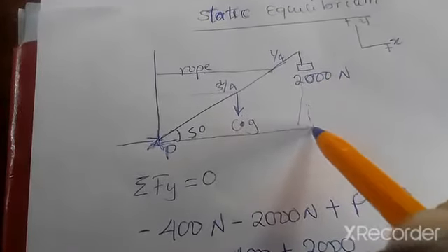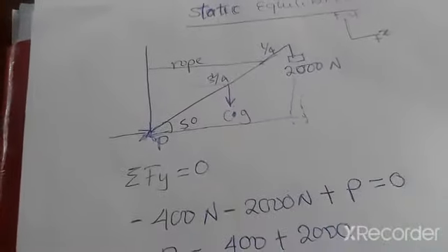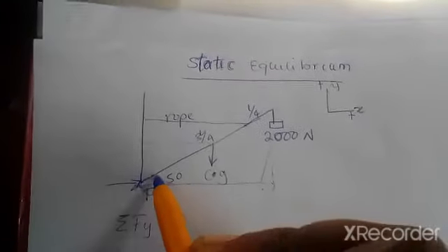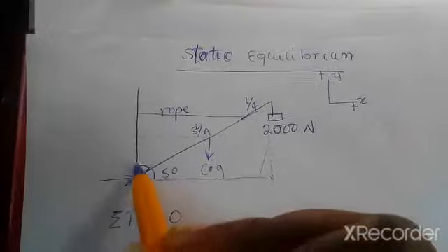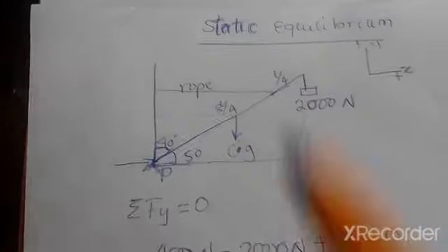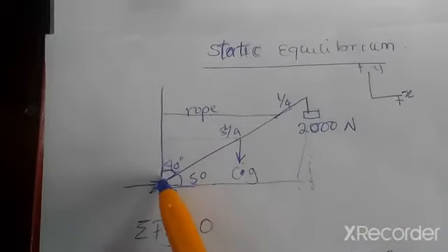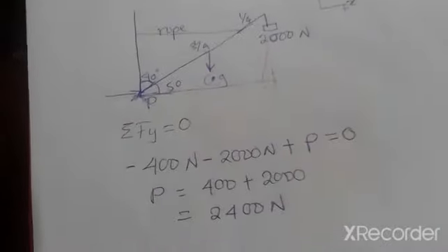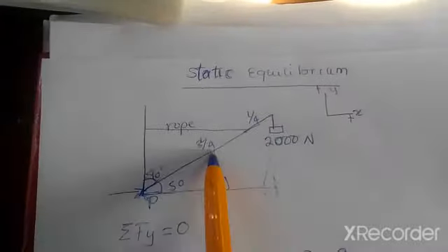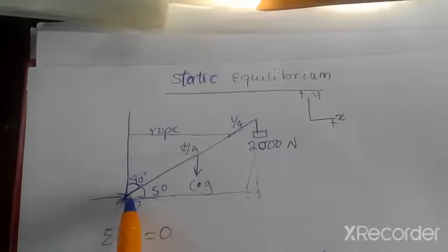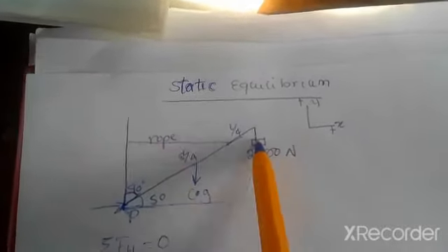So if we draw a line like that, then we'll have this distance. Okay, so now, sorry, there's a bit of light here. I'll be working with the force here, since this is a perpendicular distance, meaning I'm going to have a 40 degrees here. So I want to be working with this angle so that it will be easier for me to calculate these distances. Like I said, this is the perpendicular distance for this force, this is the perpendicular distance for this force, and this one here will be the perpendicular distance for this force.